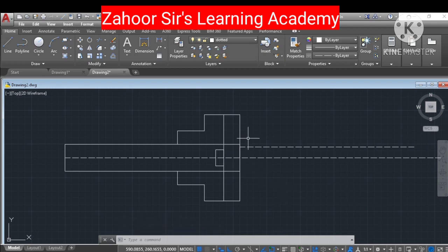Now on this center line, I need to draw the other shaft. It will be the same as we did on this side. I will take a line command, but before that, I will go to the dotted line layer and switch to continuous. So I have kept it at continuous lines. Now I'll go back to the line command, and from this point I have to go 20 mm up.